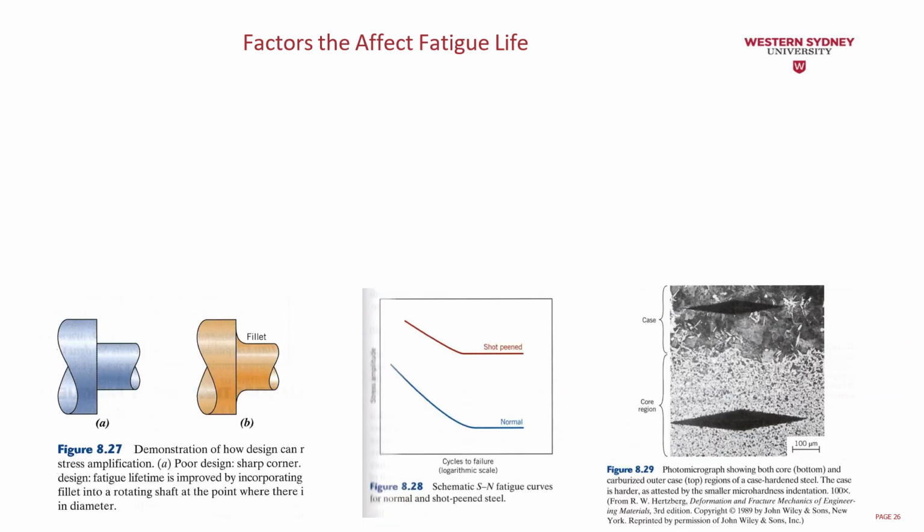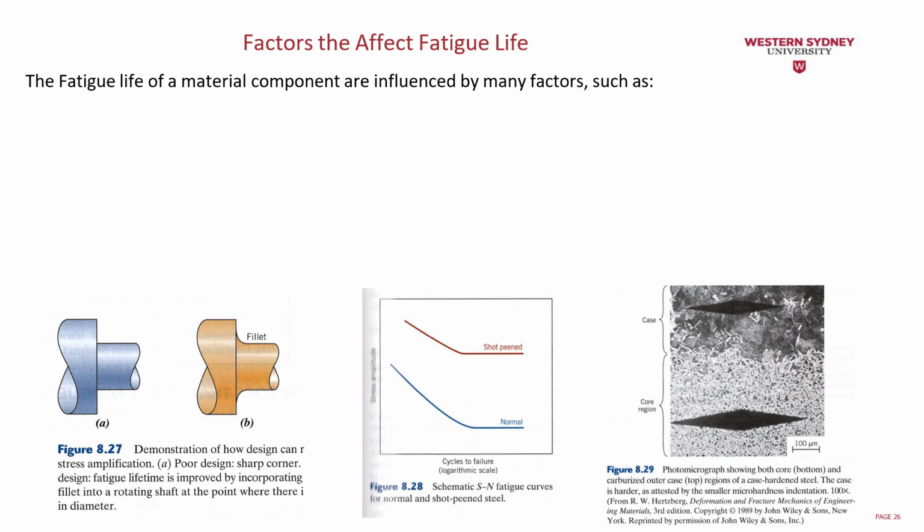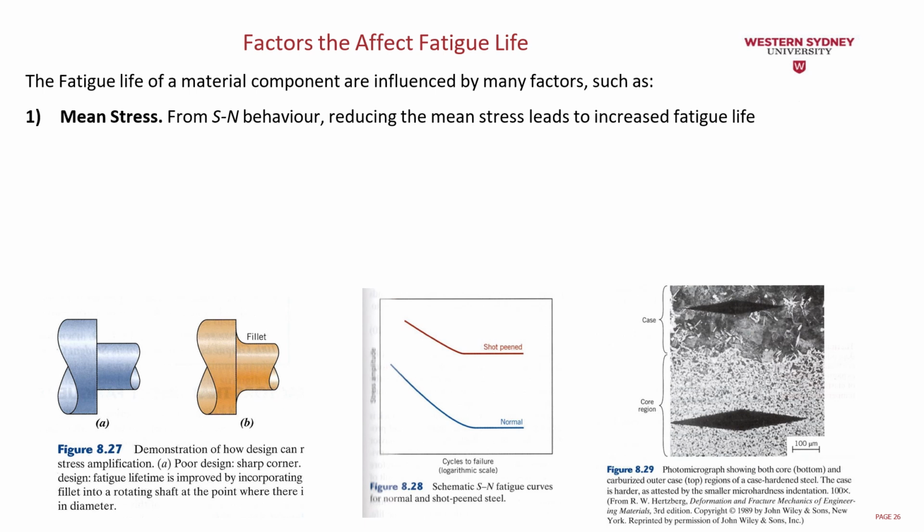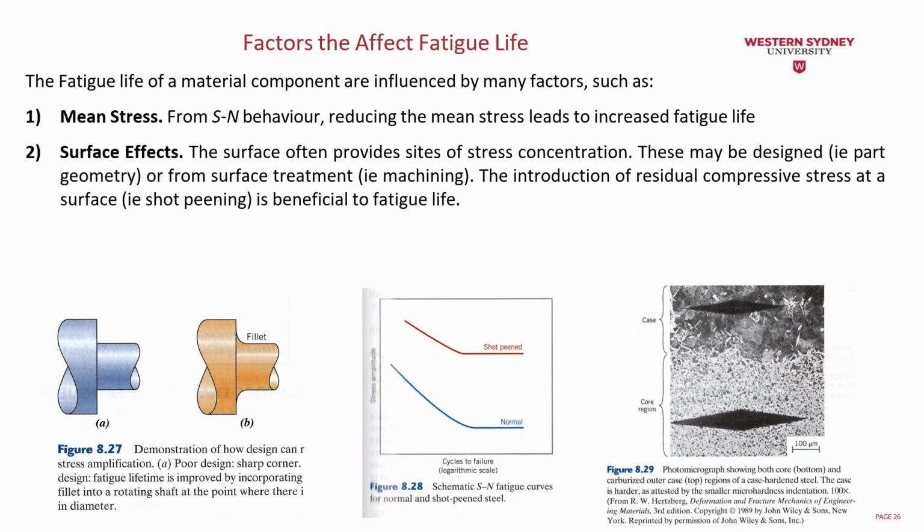The factors that affect the fatigue life: the fatigue life of materials and components is influenced by many factors. The first one is the mean stress, and we saw that the higher the mean stress is, the fewer cycles will be achieved. From the S-N behavior, reducing the mean stress will lead to an increase of the fatigue life and vice versa. The surface effect, where the surface often provides a site for stress concentrations, and this may be designed